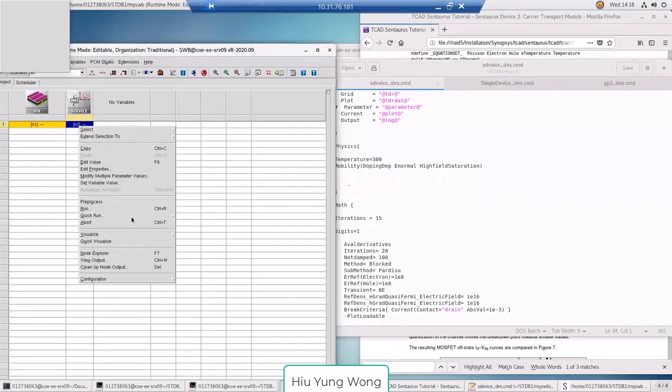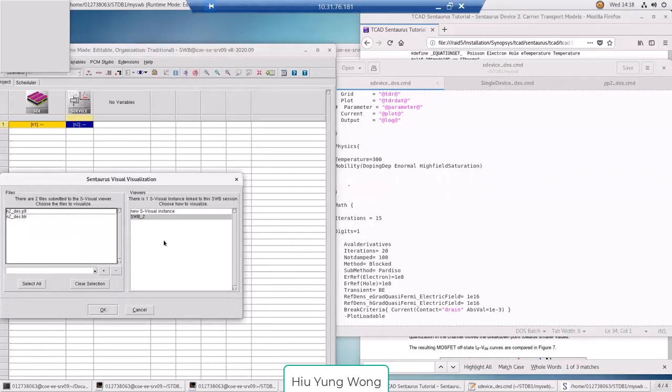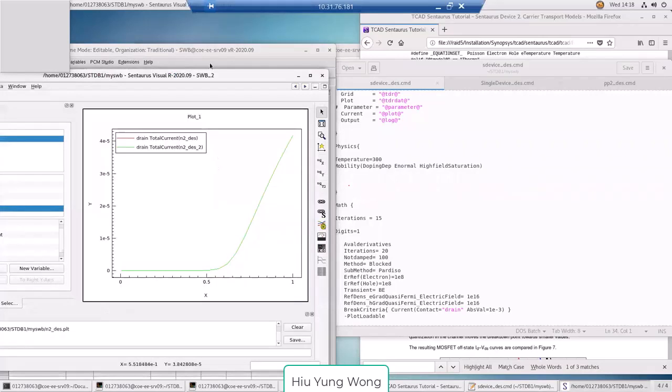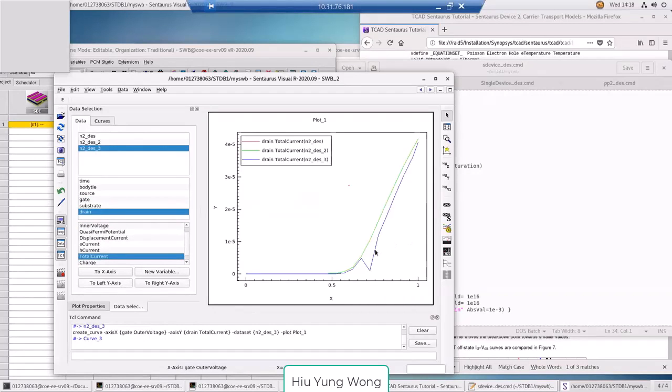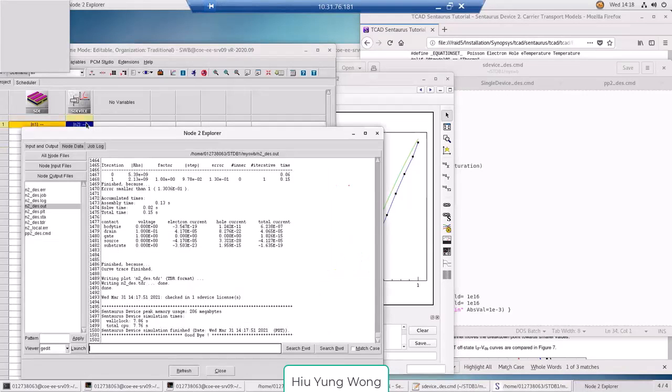Okay. I was hoping something bad would happen, but it does not because this problem is too easy for convergence, right? So I try to plot gate voltage. First of all, I really hope that at least I see the result be different because it should not be as accurate as before. Oh, I'm happy, right? In the worst case, you can even get it not converge. I was hoping that it would not converge. You see, it gives a wrong solution. This is completely wrong, right? How can it reduce, right? But it still converges. Why?